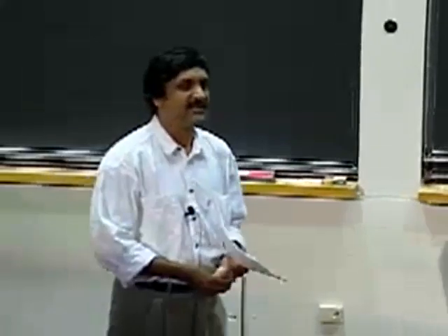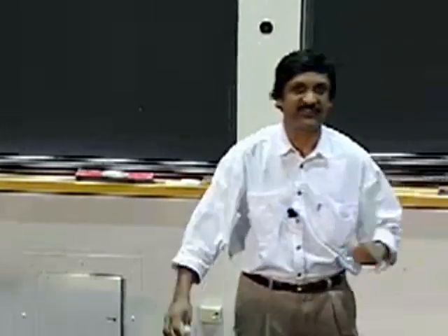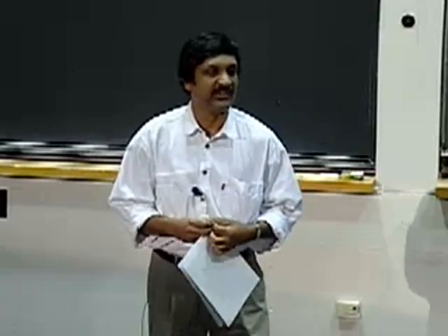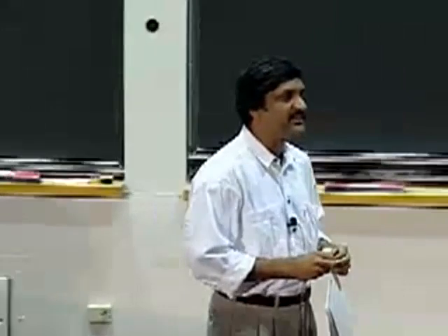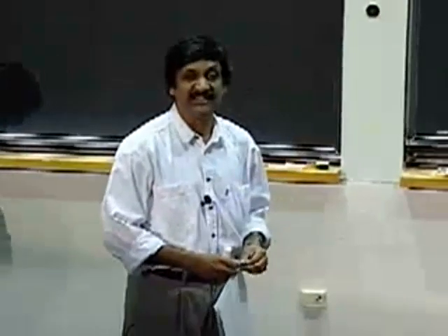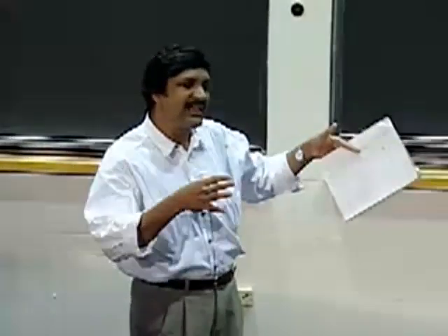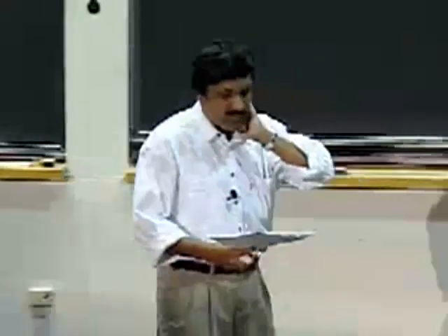And there were three tenets of the lumped matter discipline. One is that the rate of change of flux was going to be 0 within our circuits, not inside elements, but in the circuit itself. And second, the dq by dt was going to be 0 outside the elements. And third, something we did not dwell upon in the course, but it's certainly present in the course notes, is that the speeds of signals that we are going to consider are going to be much slower than the speed of light. Okay, so we're going to be working in a realm where we were going to be well slower than the speed of light. Okay, so starting with that, let me walk you through